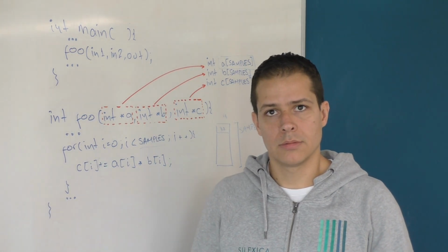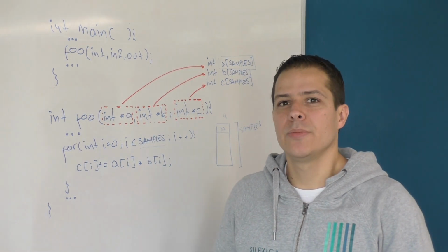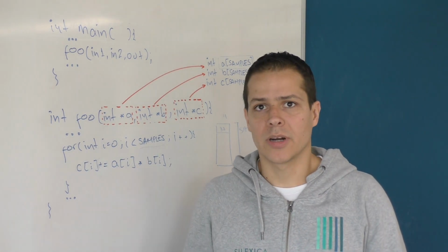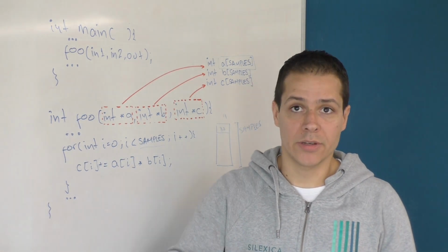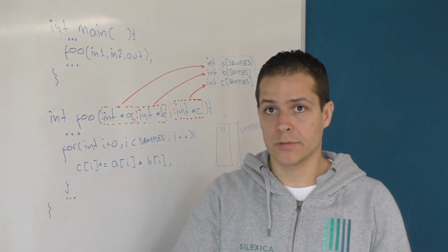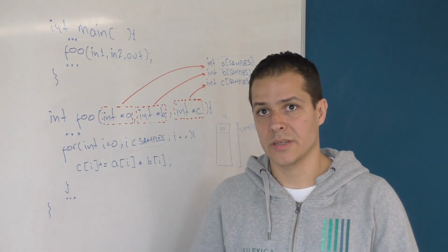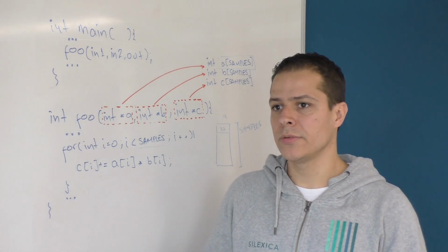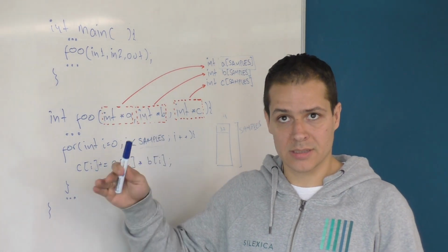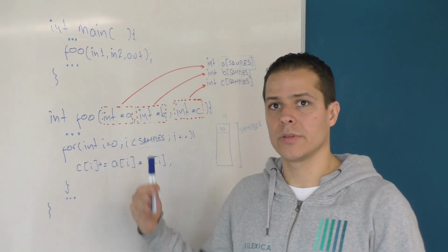What happens in something like an AI chip? How does it change there? AI is a bit more complicated because it's a rapidly changing market. I mean, the network architectures are not fixed. Also, the precision of the networks are not fixed. You can have networks working on single precision floating point, half precision floating point, integers, and binaries. So you would have to have an extra layer or an extra tool that will convert the network to whatever you want to implement and then put it through the HLS.